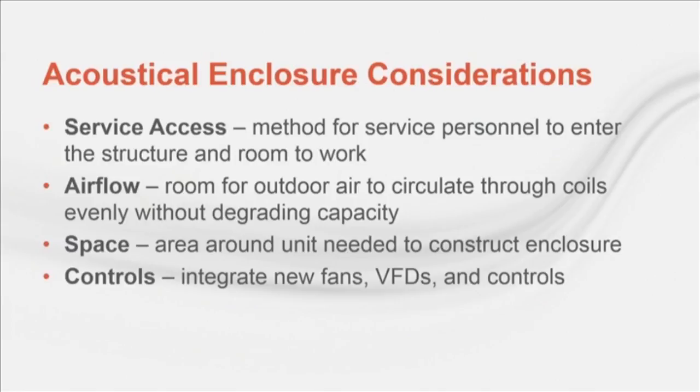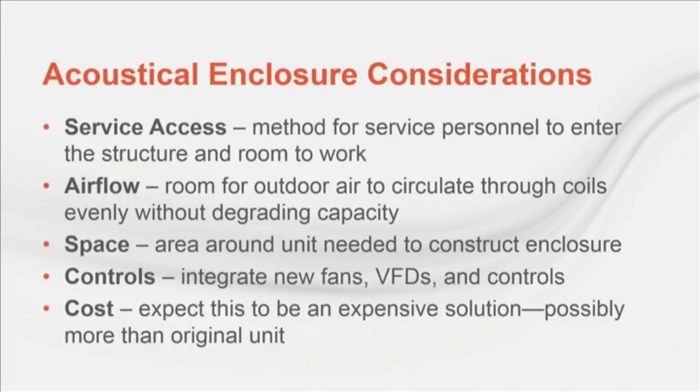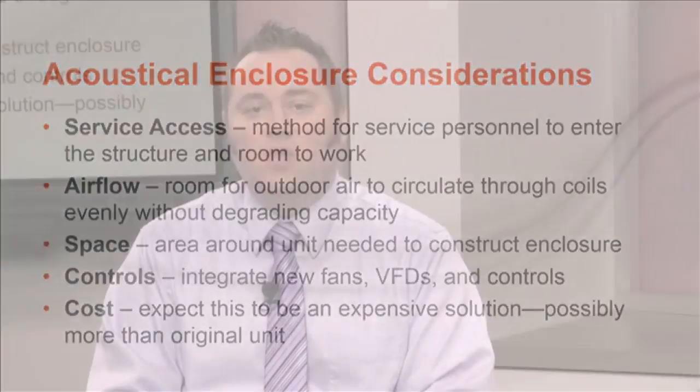In addition, most HVAC units change airflow with load. This requires the added fan to be capable of variable flow and coordination between the added fan and the unit controls. It's easy to see that this is an expensive solution. In many cases, the attenuation will cost more than the original unit. With these things in mind, you can see that this is a last resort.